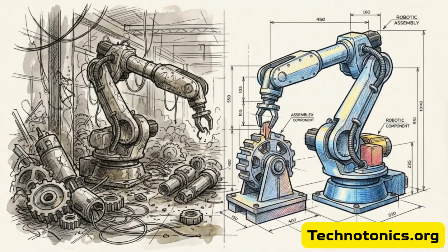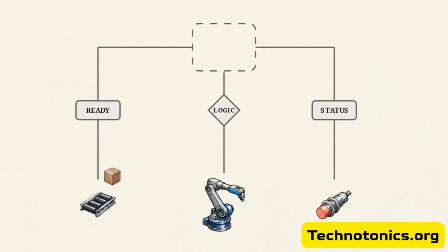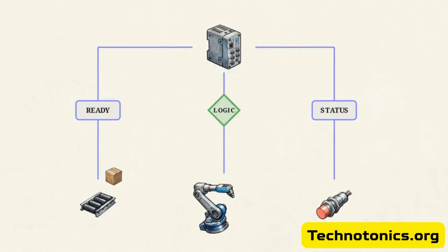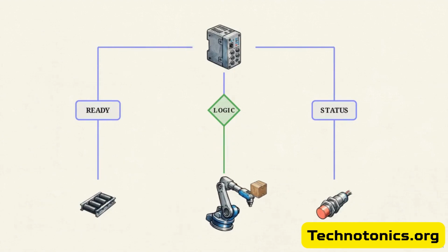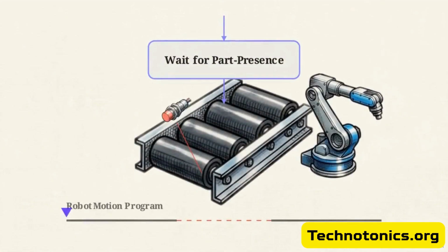A robot's physical movement is dictated by the logic commands it receives from the broader automation stack. Layer 4 integrates this external control logic. This requires integrating the Programmable Logic Controller, or PLC. This maps digital signals to the robot, reflecting the station's physical interlocks and readiness states. Signal-driven sequencing ensures the digital twin behaves like the real cell, pausing and resuming operations based on complex manufacturing variables, not just a static timer.